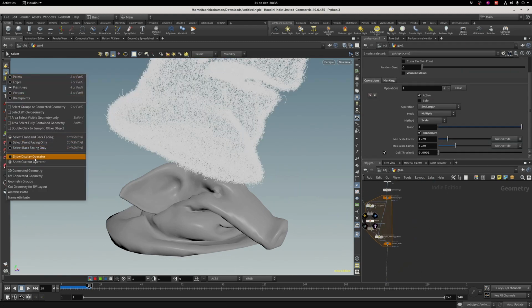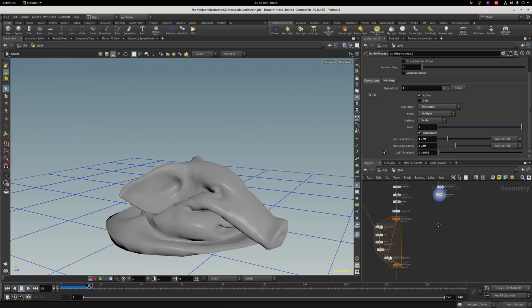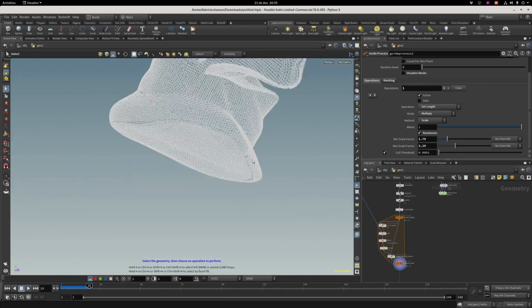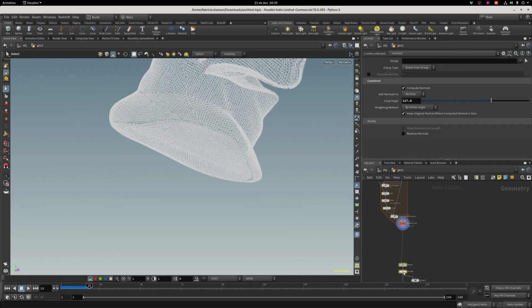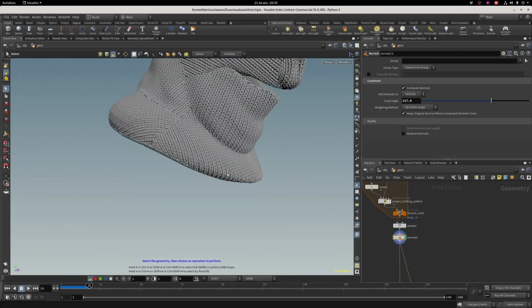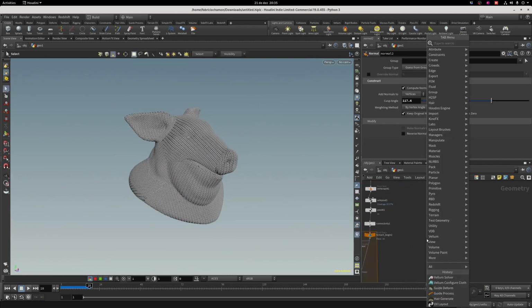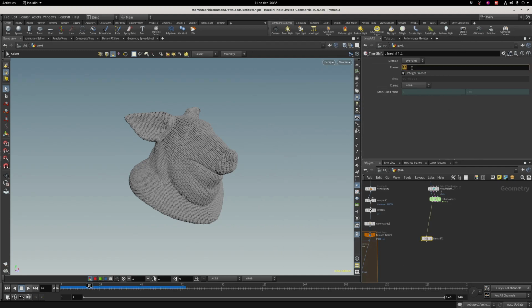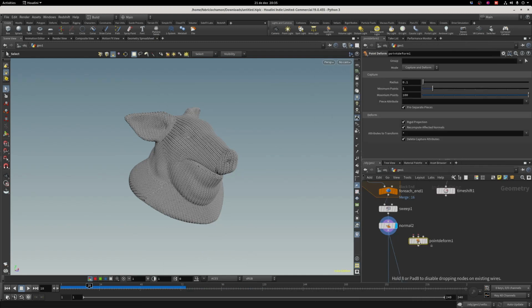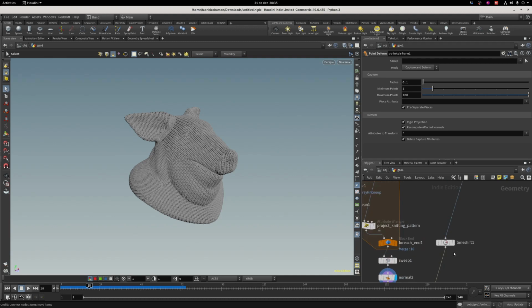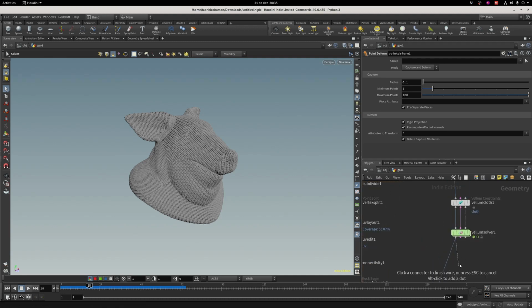So let me show the display operator. Let's first deform this geometry, or actually the sweep, this geometry. Let's deform this one to the vellum sim. To do that, let's time shift to frame 1, the rest pose, or we could even add a rest position here, but that's good. So we time shift to frame 1, and now we do point deform. We deform these using this reference pose and this deformed pose.